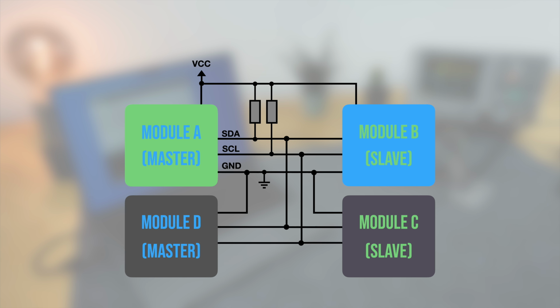Each slave has a dedicated 7-bit address. If a master wants to read or write a certain value of a slave, it needs to indicate it by sending this address over the bus together with the read or write request. Each slave listens, and only the slave with a particular address is supposed to answer.